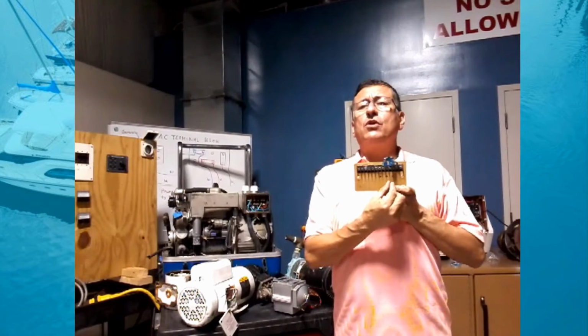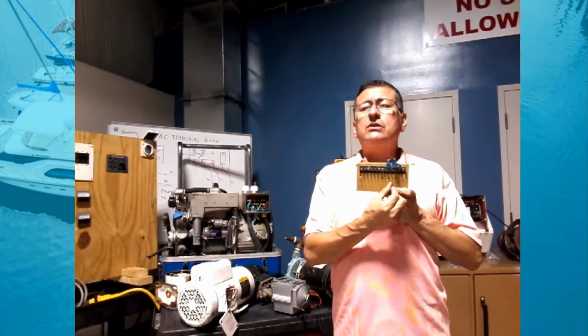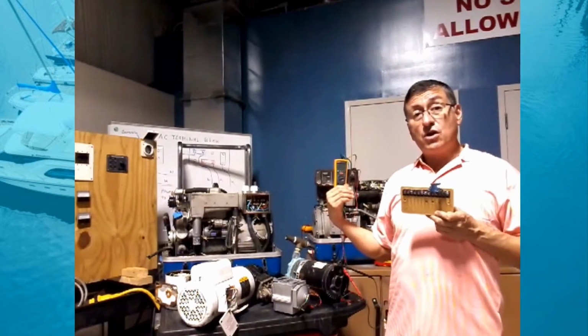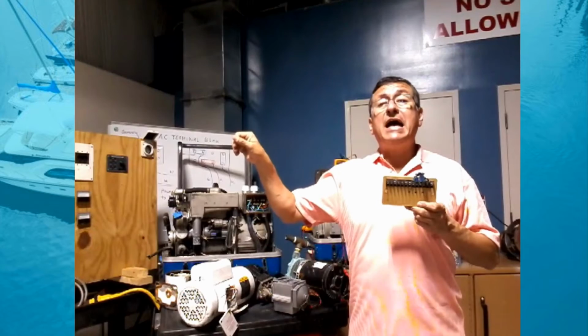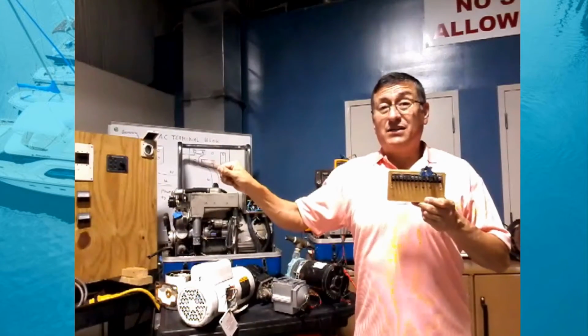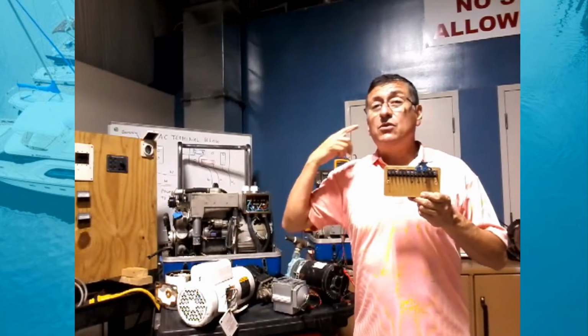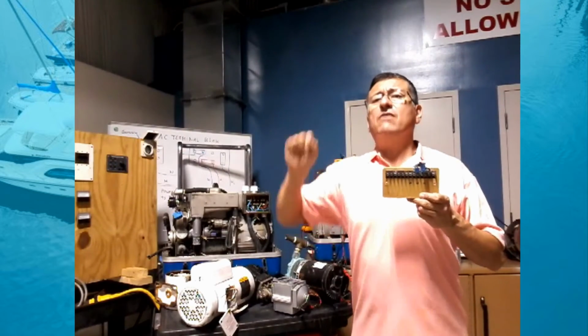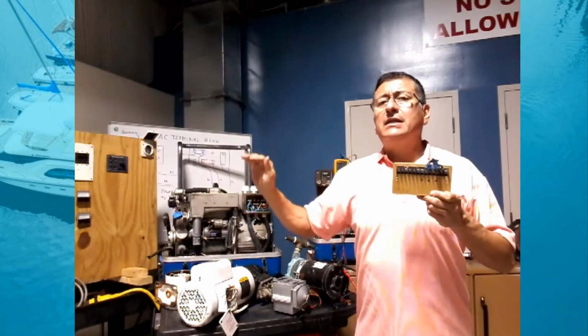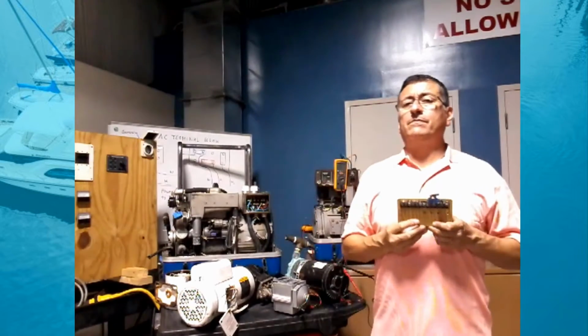Exactly the same with a small screwdriver. You adjust a little higher or lower, of course, with the generator running and with the load applied. You turn off the load, you apply the load again, and you hear if the generator recovers easily. If not, you adjust a little more until the gain is adjusted.